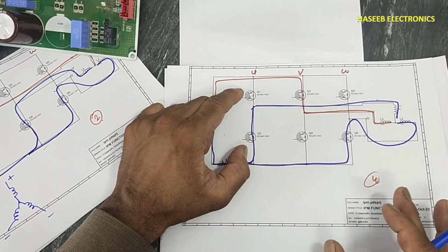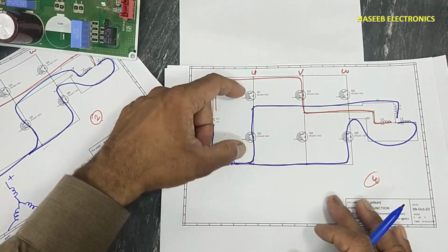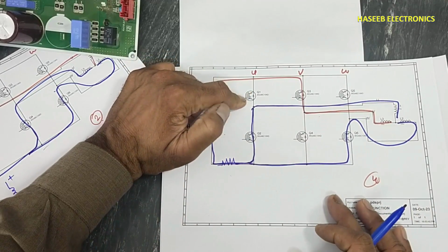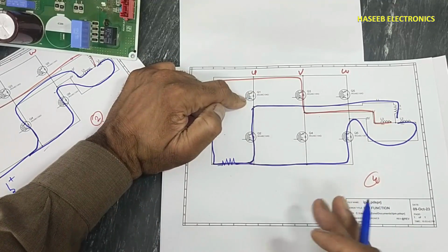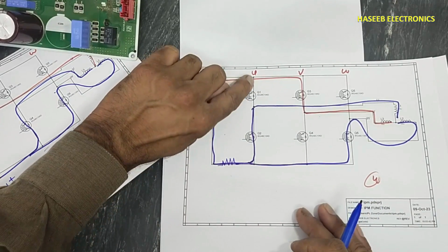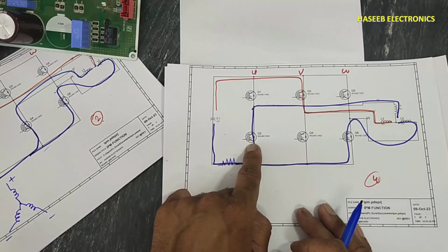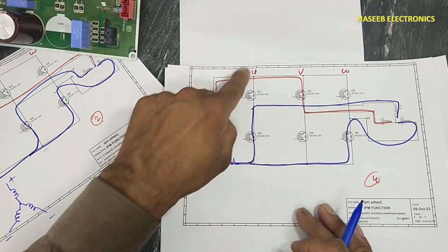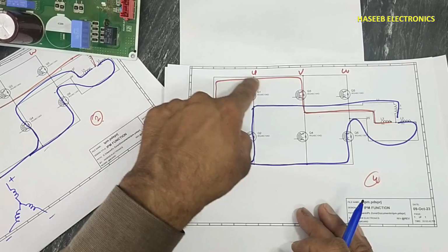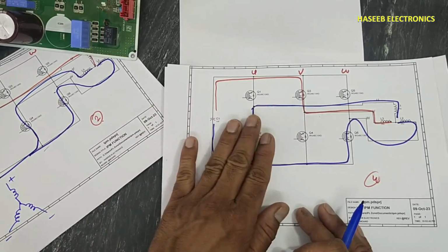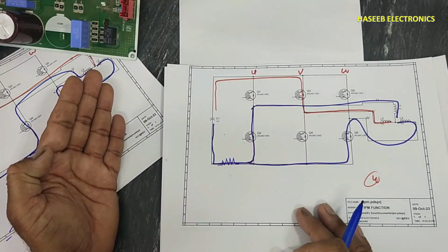Any possible reason. If one IGBT is on and it is not turned off, or it is damaged and providing permanently positive voltage, when the second side IGBT turns on, it will make a short link in the DC rail, which will cause an IPM fault.